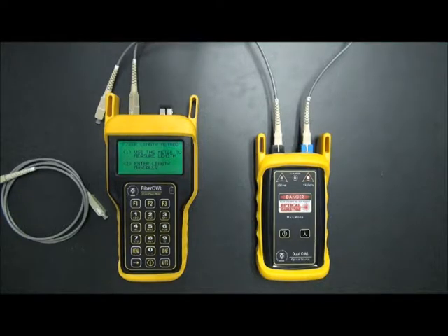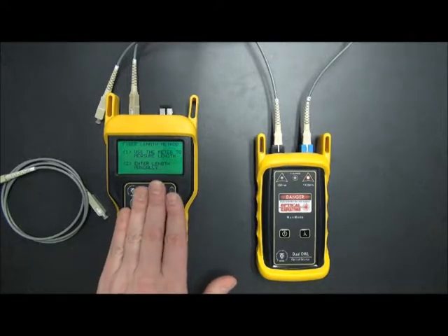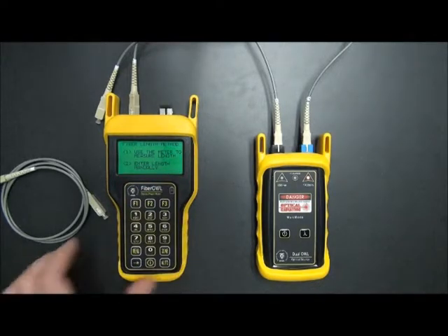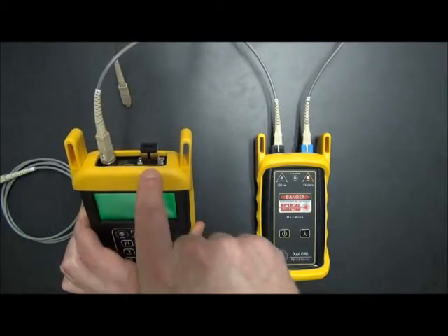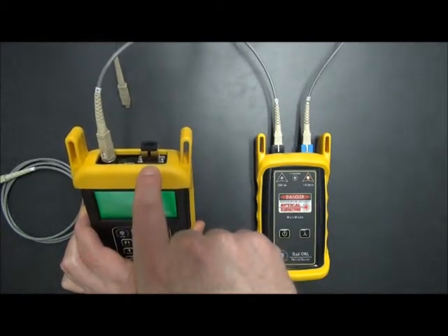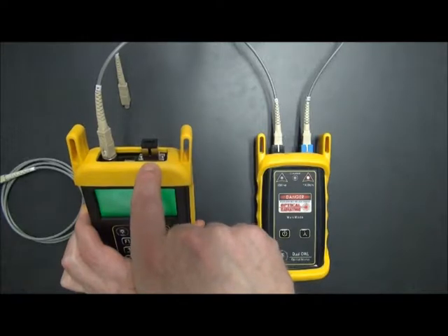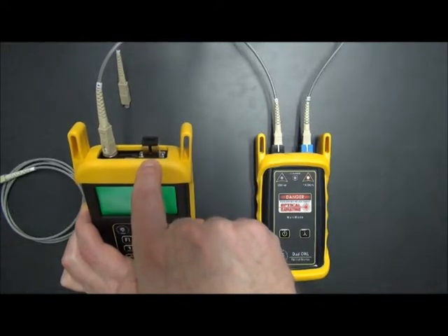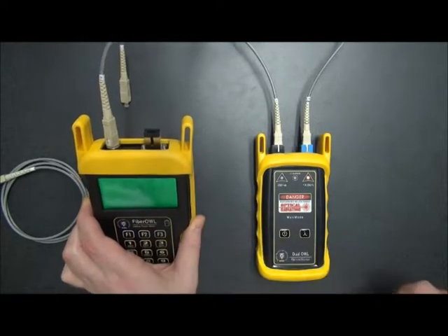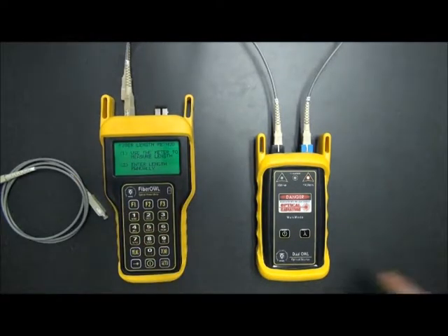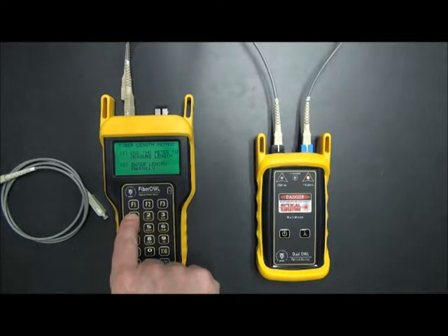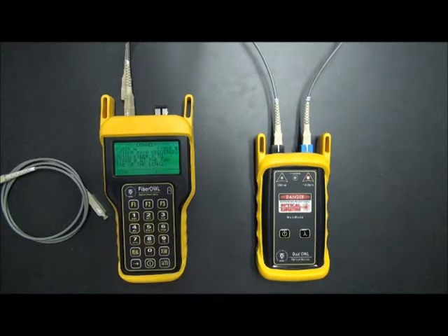However, if you do not know the length of the cable, you can use the meter to measure the length, this meter right here. Now notice that there are 2 ports here. There's a detector, which is a receiver port, and this port is used for the transmission or the transmit port in the fiber optic length test. So we're going to assume that we don't know the length, and we're going to use the meter to do that. So press 1 to use the meter.